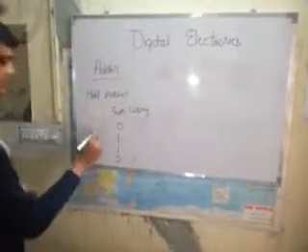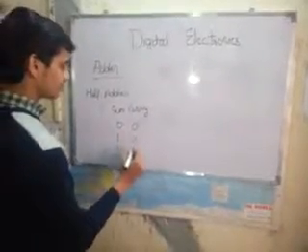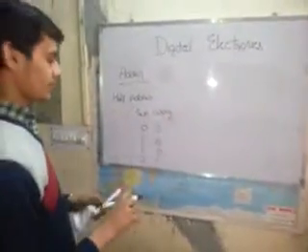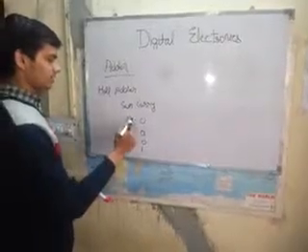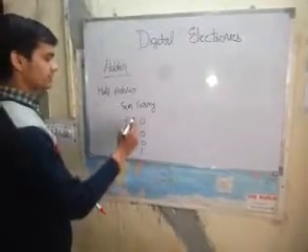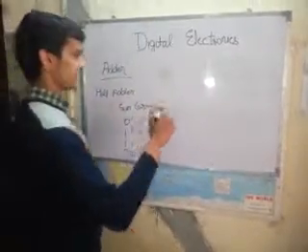While we are adding 0 and 0, 0 and 1 and 1 and 0, we get no carry, so it is 0. Now for this kind of circuit we need to design a circuit using AND gates and NAND gates. So this is the table what we have to design. So for sum and for carry we have to design a separate circuit.